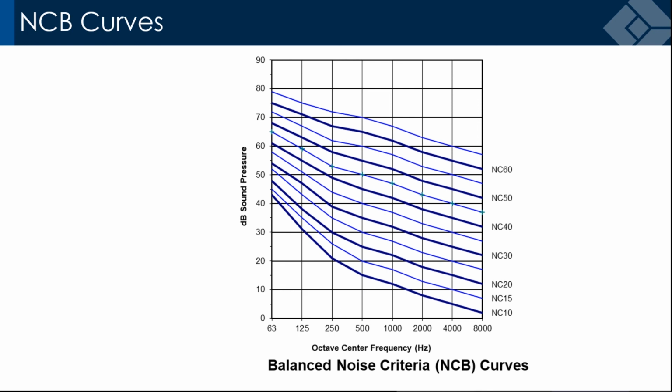The most important things I would take out of this one are, like I said before, how to describe the sound that you're hearing in a problem, and really the correct information that we need if we're trying to help design or determine an acoustical problem. Being sound power, if that's the reference, or sound pressure level, and the distance for sound pressure level. So those would be the two things I would absolutely take away from this, but it's all good stuff.